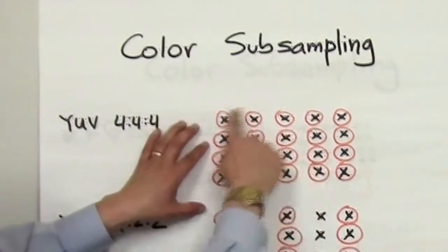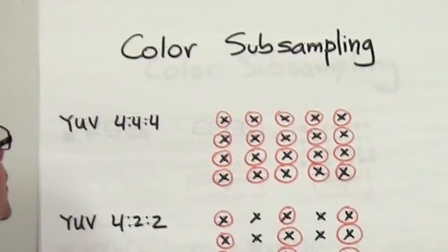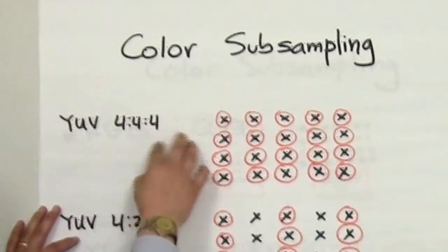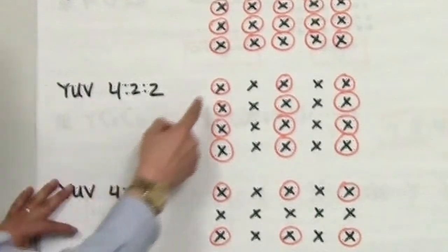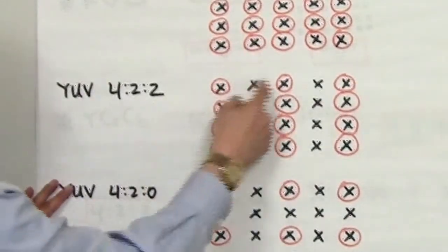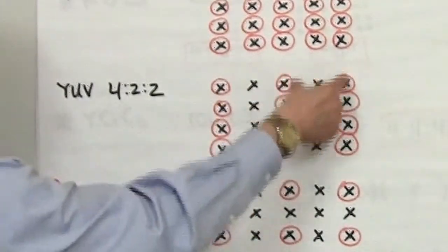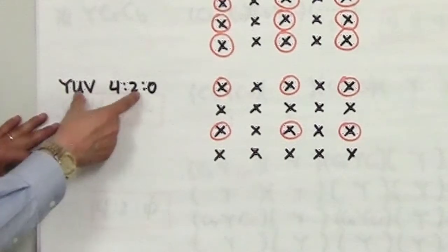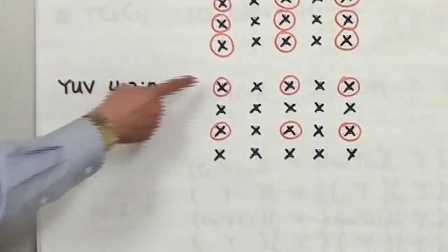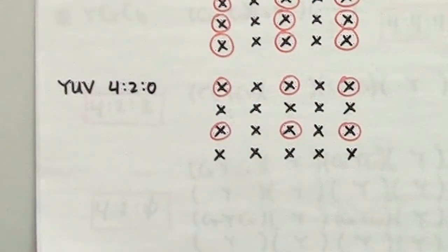So it's easy to see here that in this two-dimensional array, you have as many luminance components as you have chrominance components, and therefore the 4:4:4 sampling substructure. In the 4:2:2 domain, it's very easy to see that you have half the chrominance components in the horizontal domain, but every line has chrominance itself. And then finally, in the 4:2:0 domain, you could see that every other pixel has chrominance and every other line has chrominance as well.